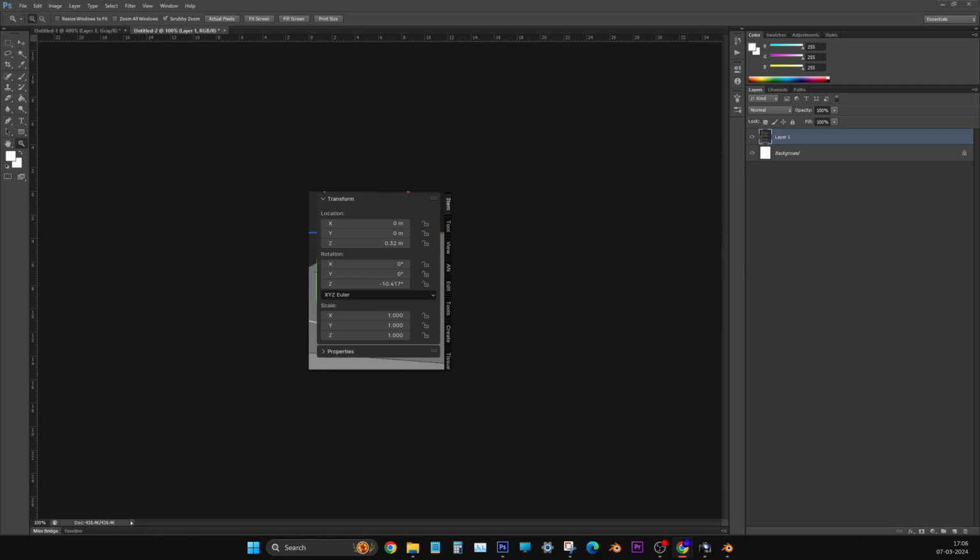Then after selection, you press Tab for edit mode, you go into its shape details; vertices you are able to see, edges you are able to see, faces you are able to see. In object mode you cannot see edges, faces and all. Components you cannot see.